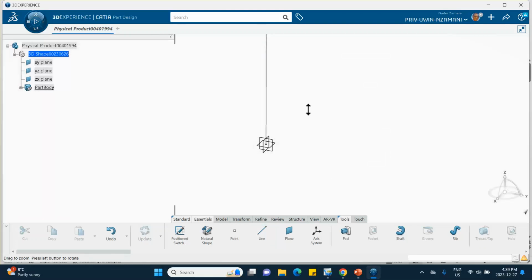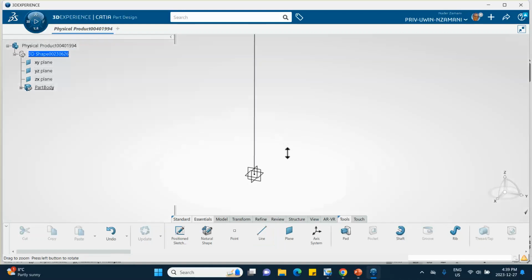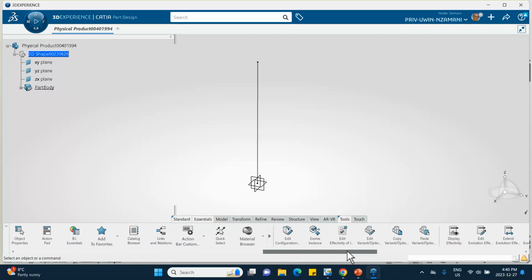Good. Now, ordinarily, if the cross section is not circular, you need an orientation point here. I did that in tutorial 4 and 5, but in 6, I said we really don't need that, so I'm not going to bother making that extra point here. Let me apply the material properties. So we go to Tools, and find the material right here.